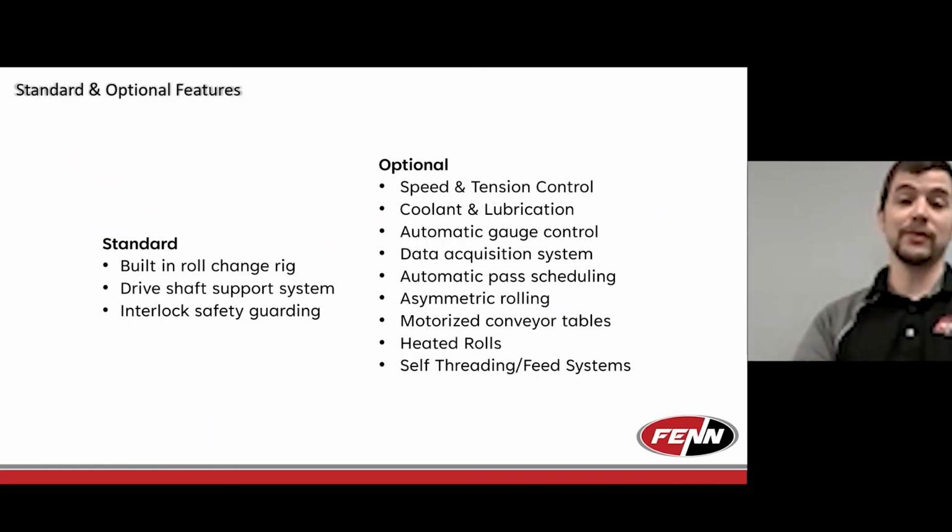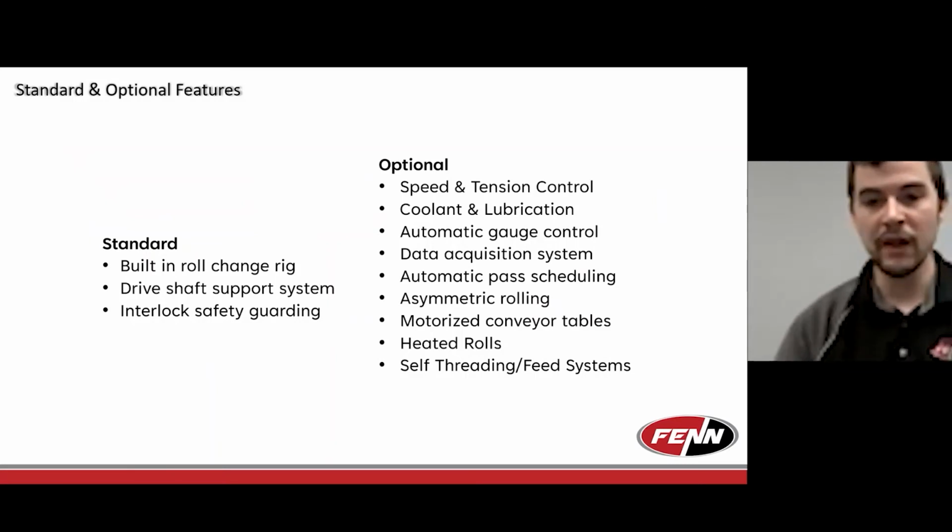Or for continuous rolling, you can have a pre-programmed schedule that you hit that loads in all the parameters at each stand in the line for what you want to run from start to finish. So that's very commonly used nowadays, and it's something that we can provide easily. And I would say it's by far more often than not included in the system.